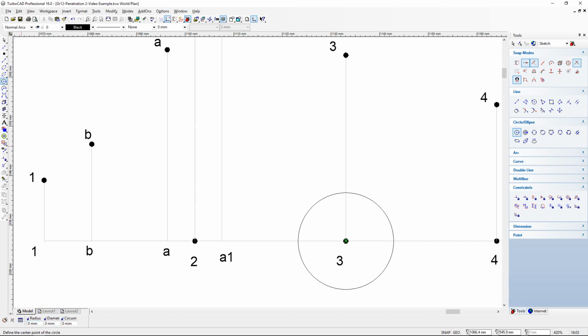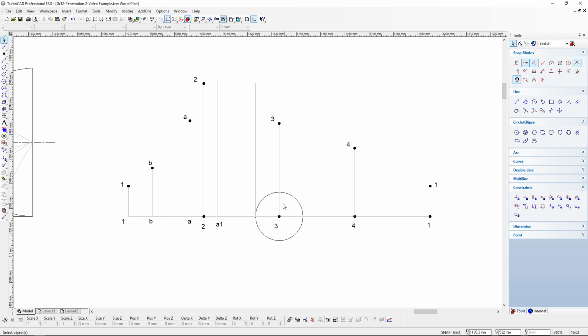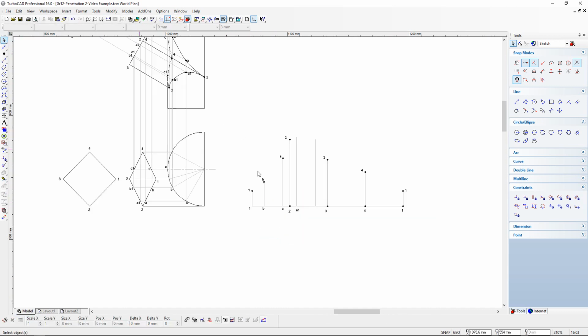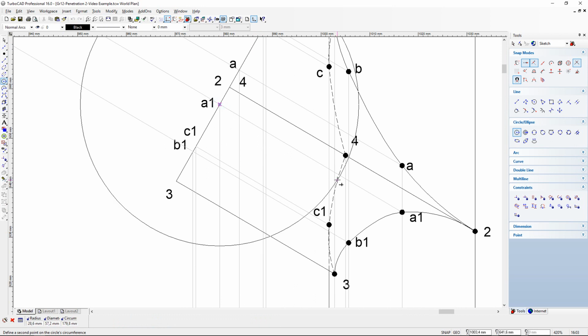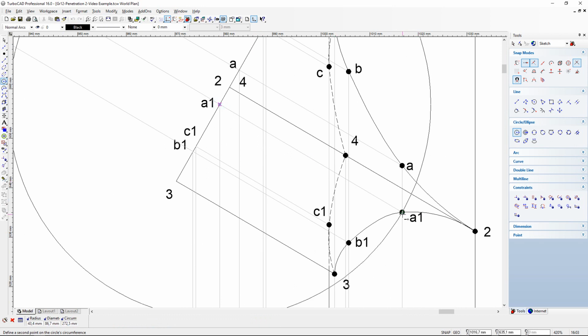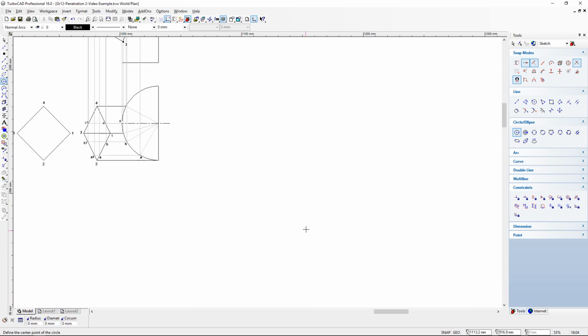And then I draw a light construction line, an indefinite length. And now I can go back to my front view and I measure the height. At this point, the construction becomes rather redundant because you just repeat this. So that's 43.4 at A1.